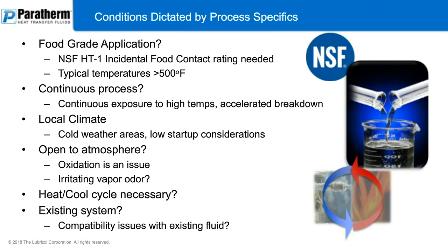You're likely going to have something in that HT1 incidental food contact. Your aromatic-based fluids are not going to meet that kind of rating. So you're limiting yourself there to the natural organics or mineral oils right from the beginning. And then you're going to want something with a capability above 500 Fahrenheit, with some cushion room there for your capability so you don't go above.